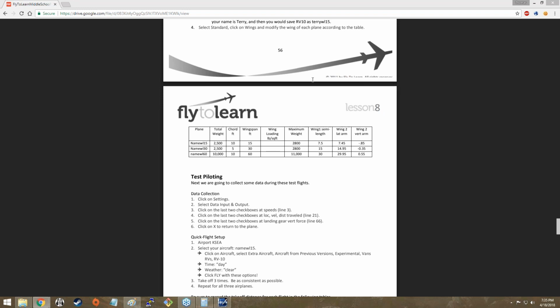That's the thing. The chord is double the size as well, but the total weight is 4 times as much. So despite the fact that we're looking at an increased surface area, the increased weight outpaces it. Therefore, no plane taking off.